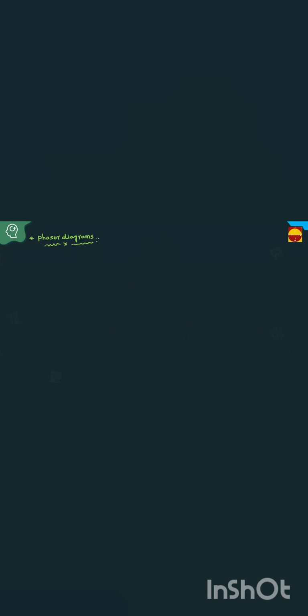I am dividing this into two cases. That is case 1: if XL is greater than XC. In a series circuit, current is constant, so I is the reference. Students, we know that the resistive drop is in phase with current. That is VR.